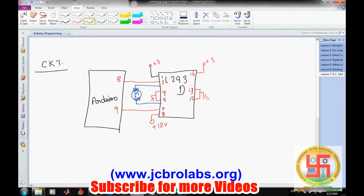Pin number 3 and pin number 6. Now what happens if we send 1 here? 1 will appear at pin number 3, that means 12 volt will appear here. And if we send 0 here, 0 will appear. So current will start flowing in this direction, and we can assume the motor will rotate in one direction. It is like we have connected this pin to 12 volt and this pin to ground.